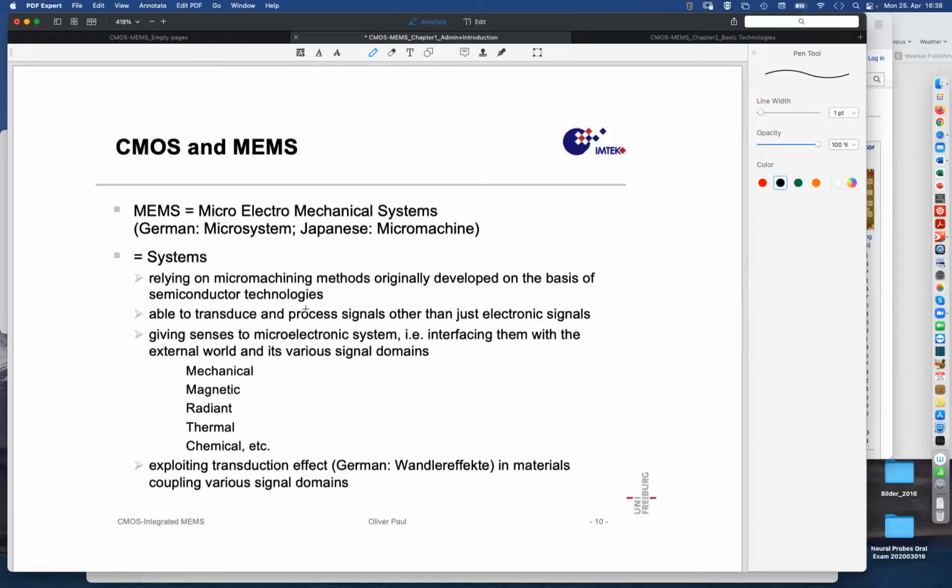There have been slower and slower slopes, and then we are reaching really fundamental limits with gate length of 3 nanometers. I mean, there is not much left. An atom has 3 angstrom, 0.3 nanometers. So 10 angstrom diameters, large microelectronic structures is pretty close to the limit.